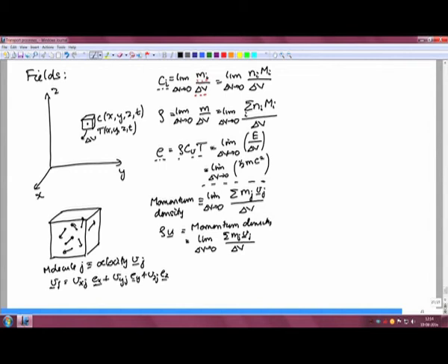The thermal energy contains only the fluctuating velocities, which is the difference between the molecular velocity and the mean velocity. So, that is the distinction between the thermal energy and the kinetic energy of the fluid. The mechanical kinetic energy of the fluid is based upon the fluid mean velocity, whereas the temperature, the thermal energy, is based upon the fluctuating velocities of the molecules. That is the distinction.